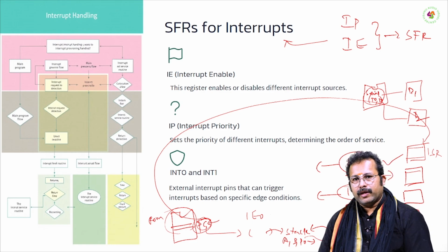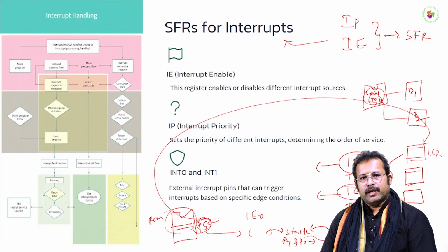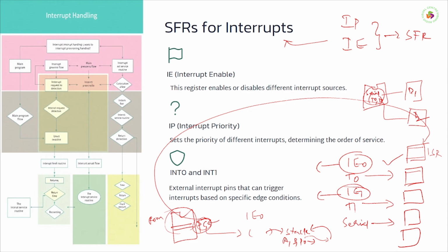It will move to the subroutine location and execute. Once the program's execution is done, the last instruction is return. Upon return, context switching will happen. It will come back to the PC's location where the previous flow was disturbed. While it comes back, context switching takes place, which means whatever information you stored onto the stack will be retrieved back. That's how it is done.